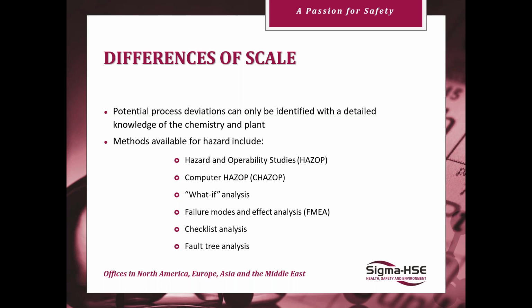So you're trying to design your process towards a safe operating envelope. That is, you're trying to provide your system with an envelope where you have your required operating temperature plus the heat of any potential exotherms, and that's got to be within the decomposition point of anything you've got in that vessel. So that gives you your safe operating envelope. Obviously, the wider the operating envelope you can provide, the better, and you are aiming for any small changes to the process not to have a catastrophic outcome.